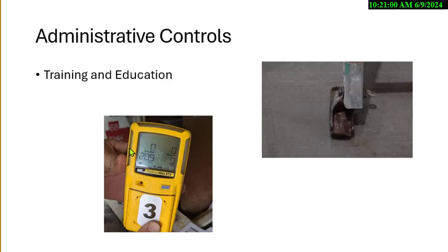So in confined space, they require you to do a bump test, which uses a calibration gas. We're going to verify that these 4 alarms are going to work. We've got alarm 1 here, 2 right next to it, then 3 and 4. By using calibration gas, we're not calibrating, we're just testing it before we use it. It goes and sets off all 4 alarms.